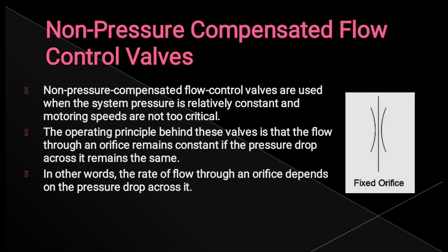Here we mainly have two types of flow control valve. The first type is the non-pressure compensated flow control valve. Non-pressure compensated flow control valves are those which are not compensated for pressure and have one fixed orifice. You can easily understand these valves by considering a nozzle.